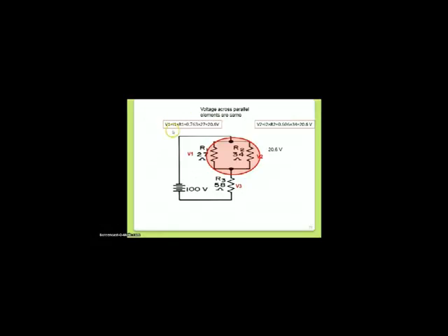Now, if you calculate V1 and V2 with the proper values, you can note that automatically the voltage comes as 20.6 volts for both V1 and V2. That is once again making clear that the voltage across parallel elements will always be the same. Coming to V3, again the rule I3 multiplied by R3, and you get the value by substitution 79.4 volts.